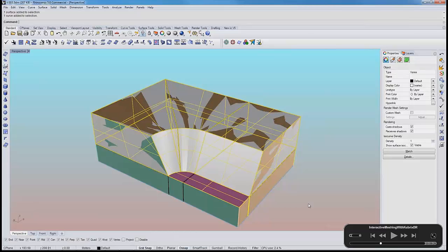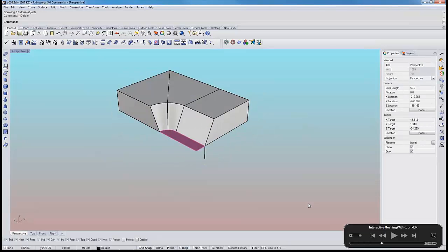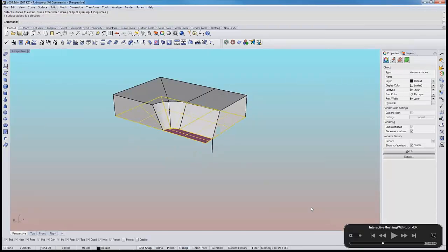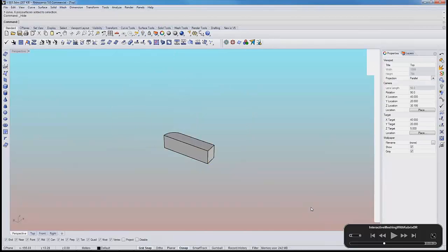to create another solid in the bottom here. I throw away that mesh that I had kept originally, and here you can see that what we have right now is one solid, two solids, three solids, and the surface here and a straight line here that we drew that will be used later on to extrude that surface. And I will accelerate this here, showing how we extract these other surfaces plus this surface, and we extrude them all in the direction of the line segments in a straight manner, and we have now this way created all the solids that we need.